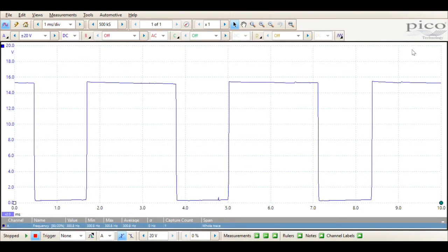Okay, so this is actually a waveform of a solenoid being duty cycled or pulse width modulated. So if I wanted to measure what that duty cycle was, what we would do is pull over our blue rulers from over here, and we would go to our first rising edge, and then we would take our other ruler over to our next rising edge. Now these rulers automatically default to 2 cycles, or 200%. But if we double click this, we can change that to 100 because we do percentages in the 100% range.